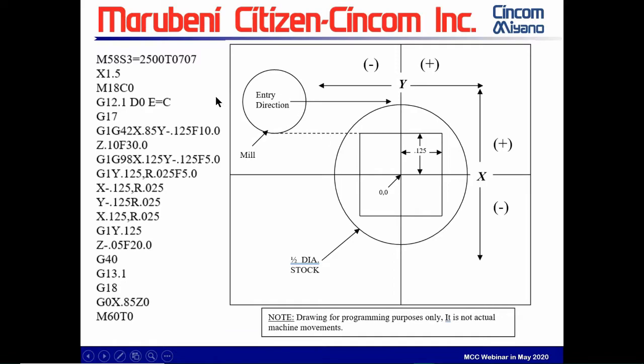That is enough distance to install your cutter compensation. You have to have a little bit extra move. Now, it is a little bit overboard, but it will install it. The next move you see here is a Y positive 125.